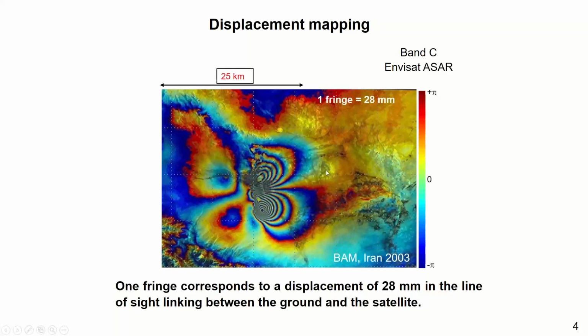So what we do is we try to understand the pattern of fringes here. Here the yellow goes to the blue one and goes to the red one. So we see here the yellow goes to the blue one. It means from here to here, the phase is decreased and it repeats the yellow here. So from here to here, we get one fringe and the phase is decreased. So just based on counting, just based on visualization, we count the number of fringes and quantify that magnitude.